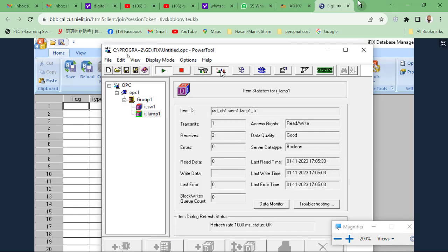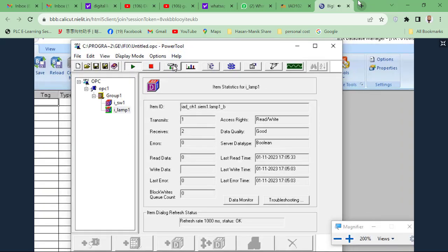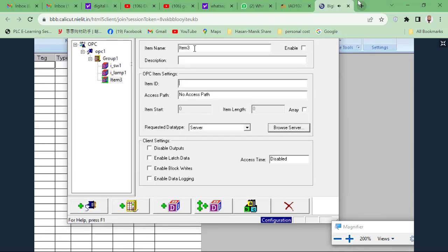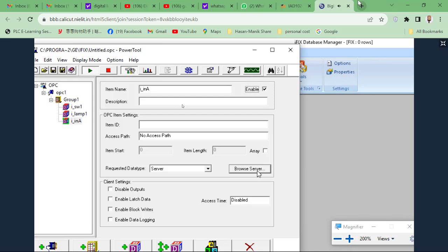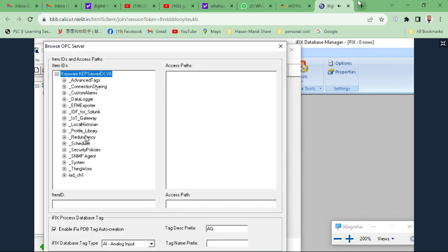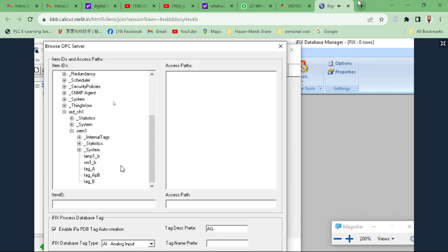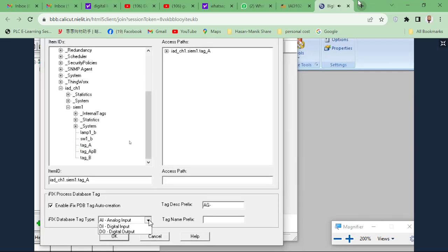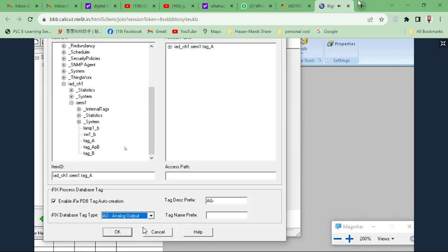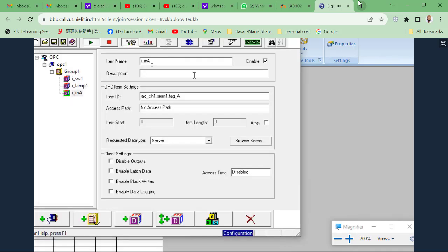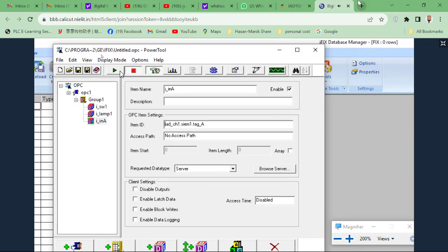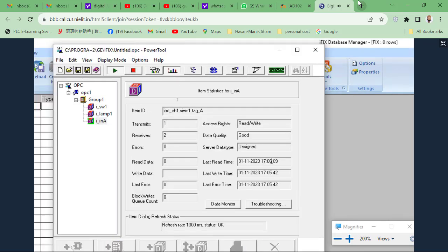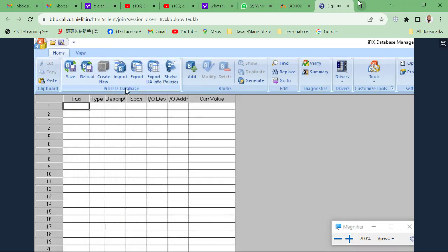That also is good. Like that we go for some analog also. Configuration, then analog, input A. Okay, iFix in A, browse, you see, browse this one, then enable, select IA Siemens, input A tag, it's analog output. Okay, so from SCADA you are writing analog output, that's why I put it here. Then save this one, save, stop, run and monitor. Now you minimize this one, automatically it will refresh and the tag will be coming.